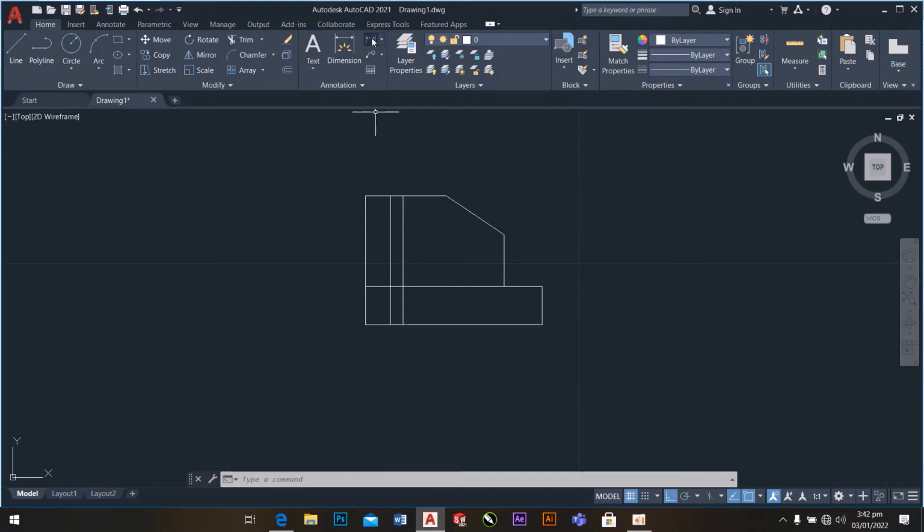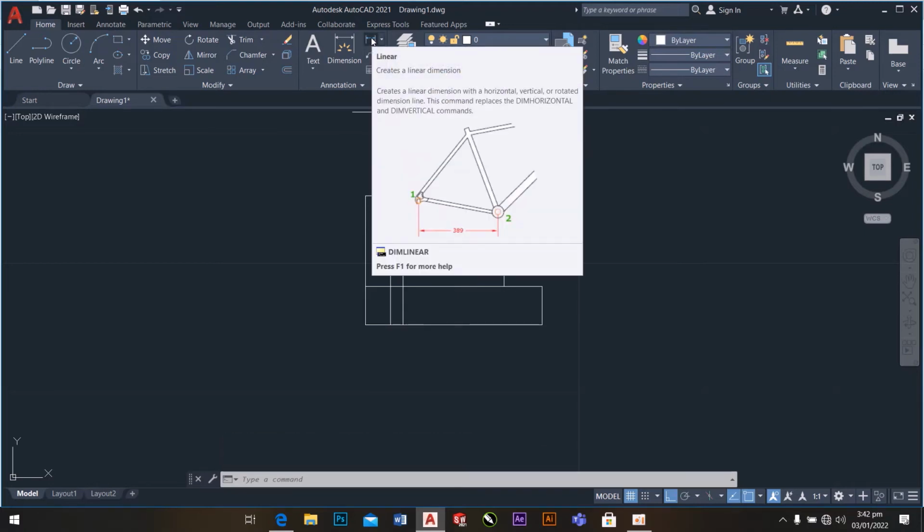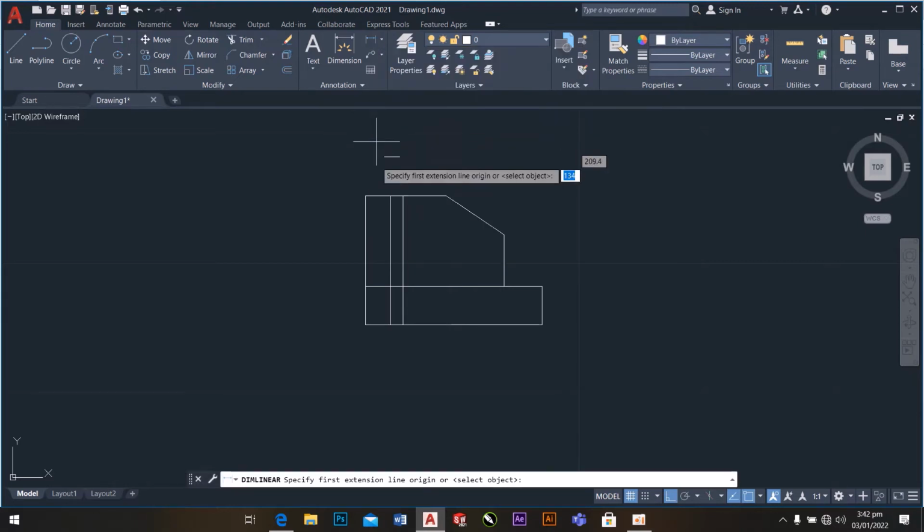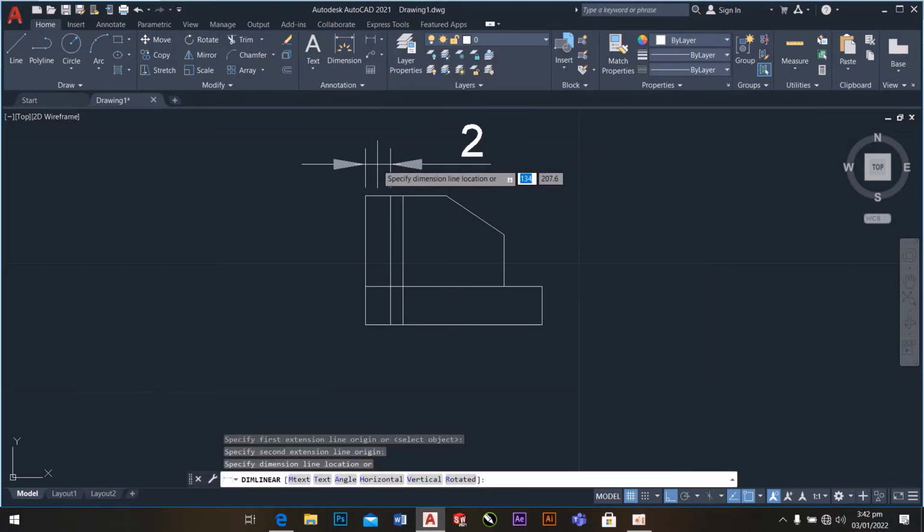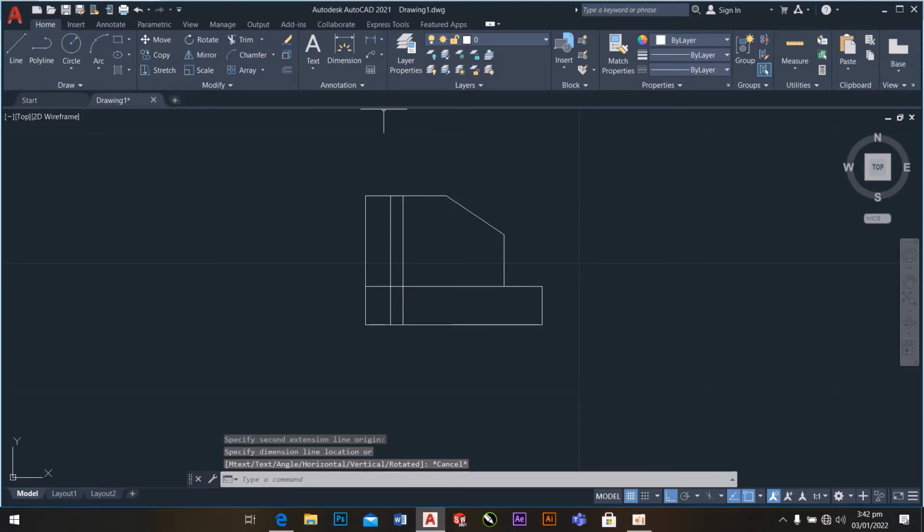So we can confirm, going to our annotation panel, the distance of the line, if it is 2 mm. So we click on this point and this point, we can see it's given to us as 2 mm. And the other one also, we click this point and this point, it is 3 mm. So now it's for us to draw our circles.